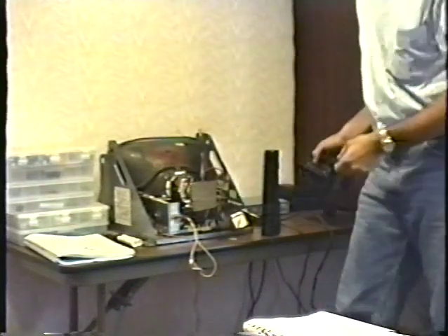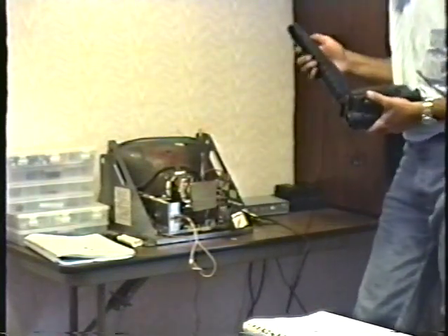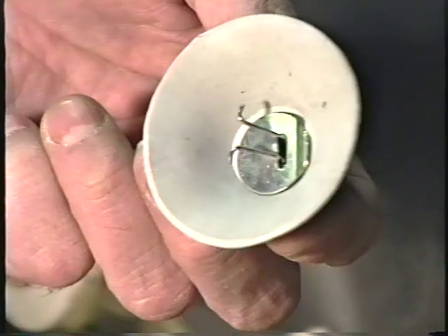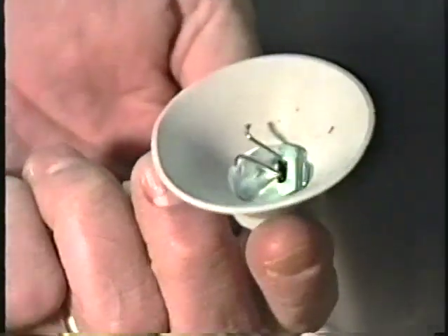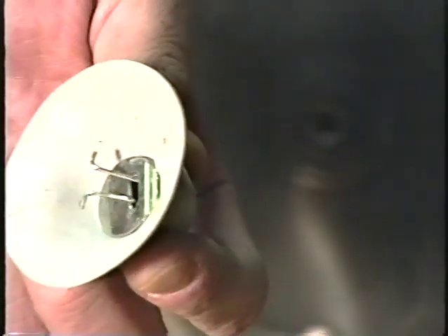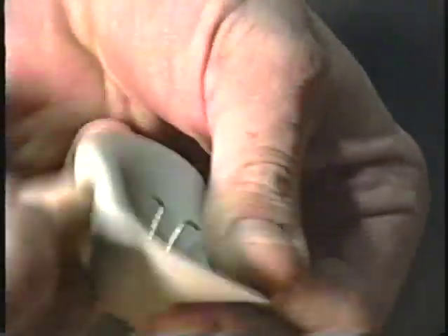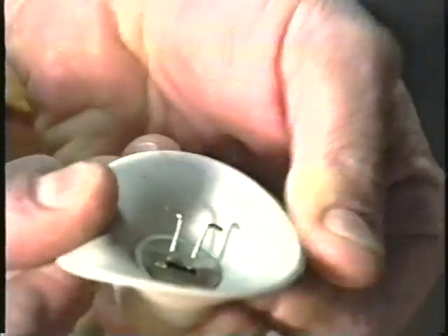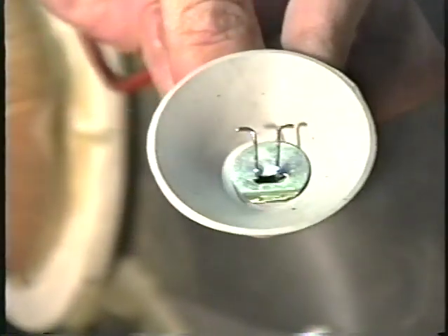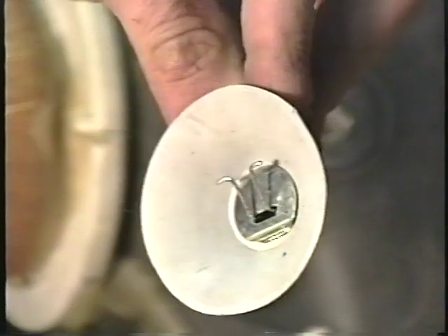Two words of caution. Number one, when you go to put the second anode back in, you see the two little fingers there? You've got to make sure that you get both of those in. Never depend on the suction cup action of this thing to hold it in place. It'll kind of act like a suction cup, like, if you put it on there, it'll hold on there, but then it'll fall off. So you have to make sure that you get both of those little fingers on there.